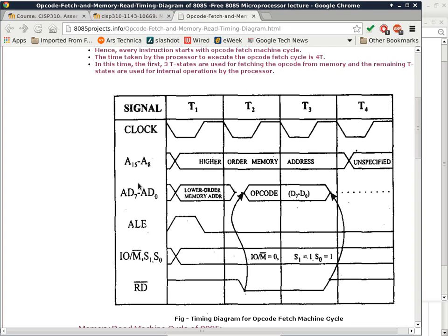If you have a single layer on the circuit board and you have to route signals, let's say this has to go here and this has to go here, well, the first one is easy. The second one, not too hard. I can kind of go around like that, right? But if you have a lot of points and they cross over a lot, then at some point you cannot do it on a single layer board at all. It's just mathematically impossible.